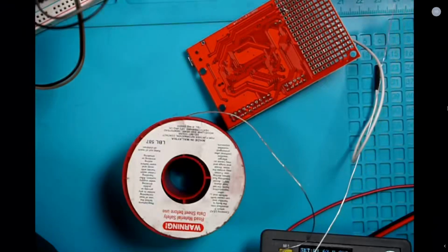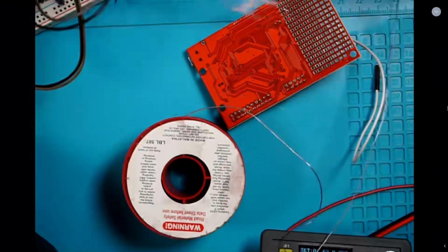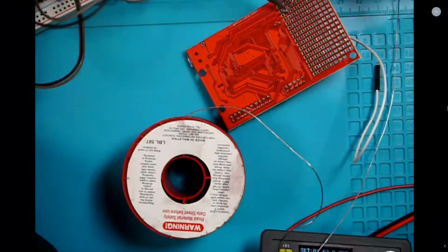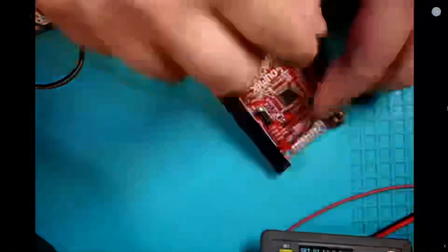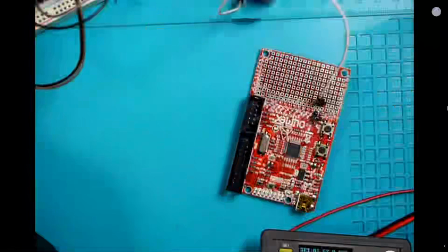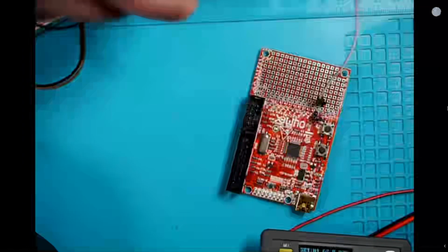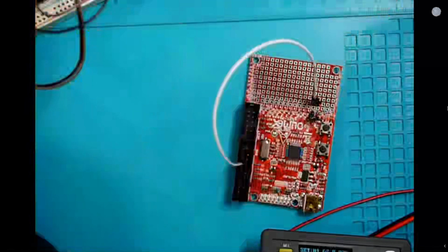Oops, sorry. I think the other one's the one that's heated up. Yes. All right, so that connection we're good to go. So now all I need to do is connect this to a ground pin. And like I said, fortunately, almost everything is a ground pin on here because we have this JTAG connector, and on an ARM JTAG, most of the signals are ground. So I'm just going to pick number 4 over here, and then we can test it.